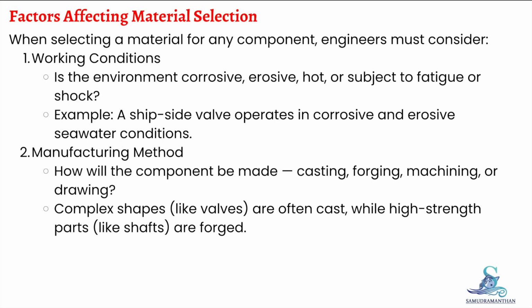Factors affecting material selection. When selecting a material for any marine component, we must consider the following factors. Working condition. Determine whether the environment is corrosive, erosive, hot, or subject to fatigue and shock. For example, a ship side valve must withstand corrosion, erosion, and impact.